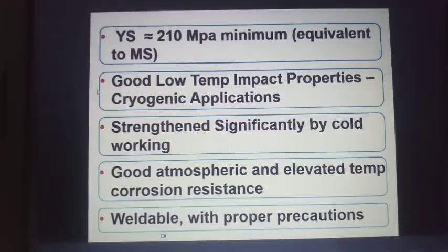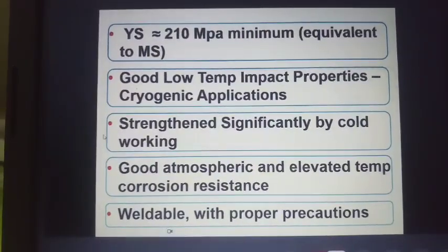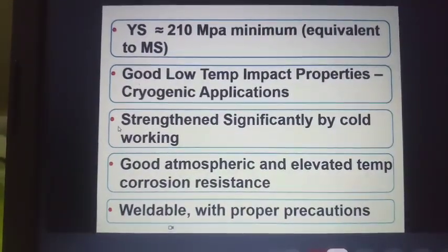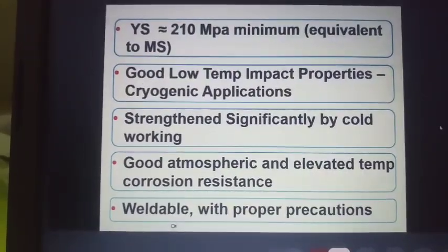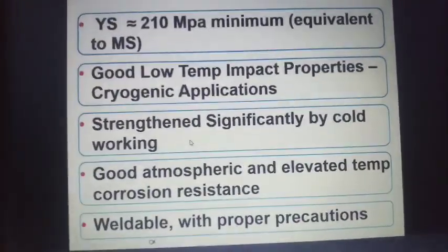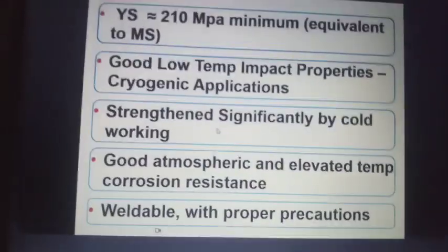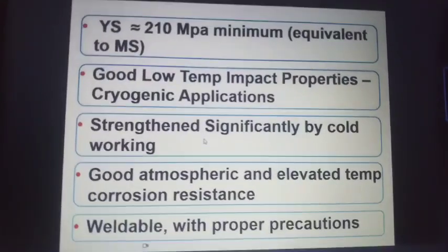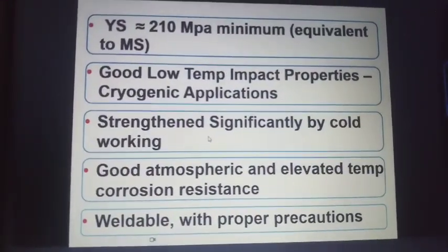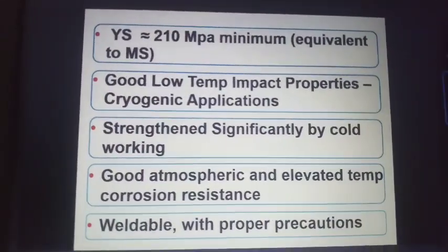But for duplex stainless steel, sir, I think we need to do impact testing always. It becomes mandatory, right? I think below minus 46. Anyway, even carbon steel and low alloy steel, at minus 46, all ferritic steels are impact tested as per code. No, there are some exemptions for plates. Generally, they don't require impact testing as per code unless the thickness is very high.